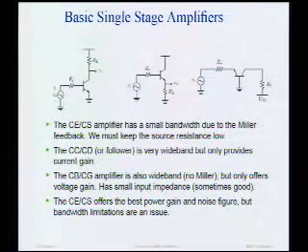And that's because each one has a weakness. Now, let's start out with the common source amplifier. The strength of the common source amplifier, common emitter amplifier, that we should mention is gain. It has lots of power gain. In this course, you're going to get into the habit of thinking about power gain. I know up to now you've thought more about voltage gain or current gain. In this class, power is money. Okay, so power gain means you have to have current gain and voltage gain, right? So the common source amplifier is good because it has both. What's bad about a common source amplifier?